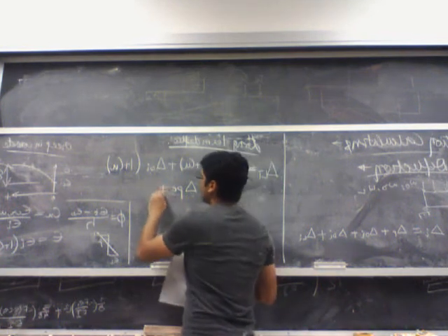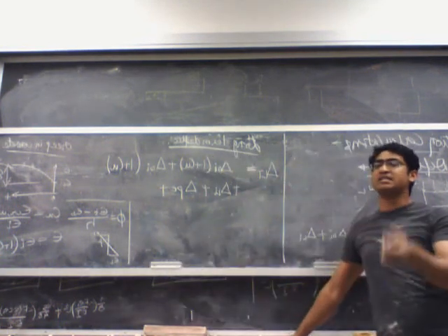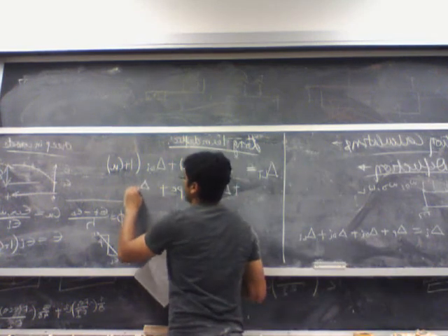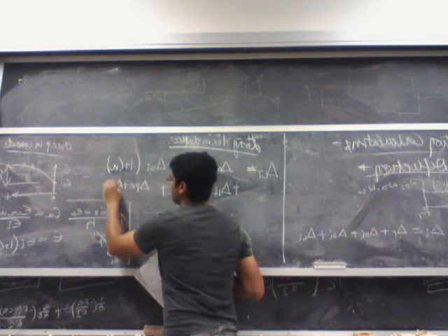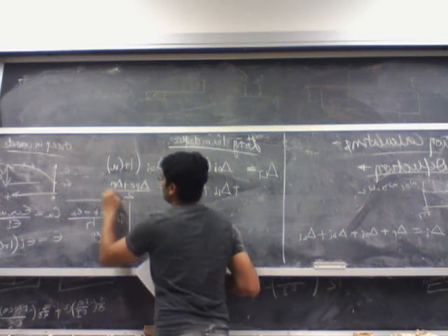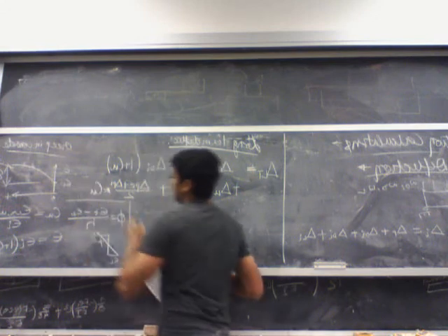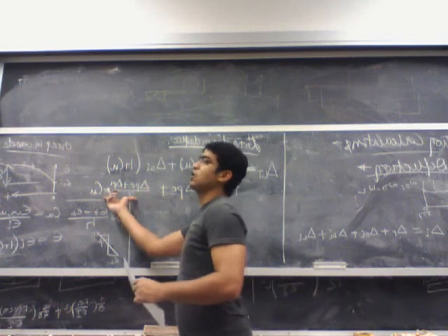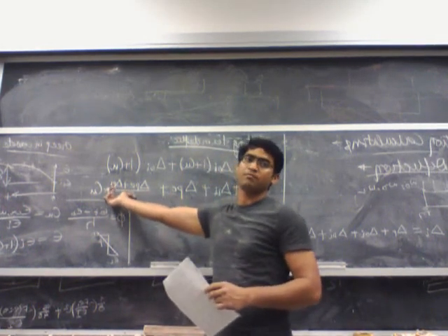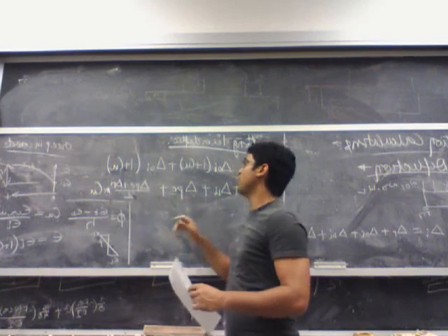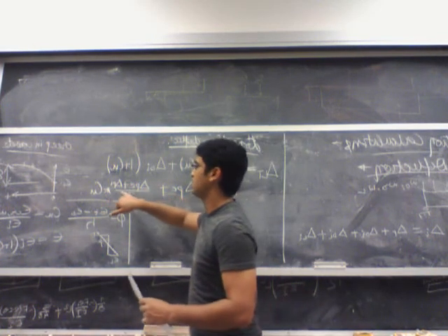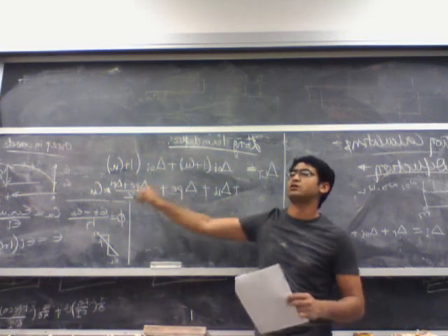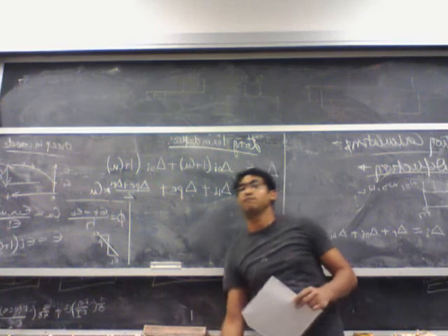And to account for the creep, you actually take the average of the initial deflection due to the initial pre-stressing force and the effective pre-stressing force. So you say delta Pe plus delta Pi divided by 2 times Cu. So this accounts for the instantaneous deflection, kind of, and this accounts for the additional deflection due to creep. And this is just an approximate value, because both the concrete is creeping over time, plus your pre-stressing force is also decreasing over time.